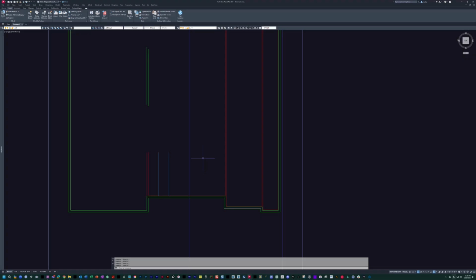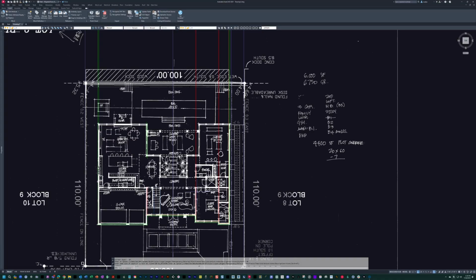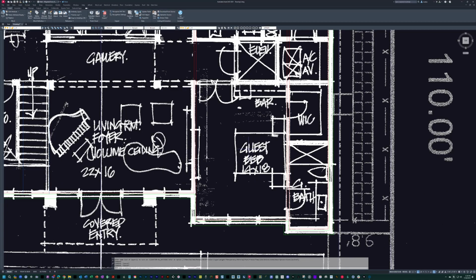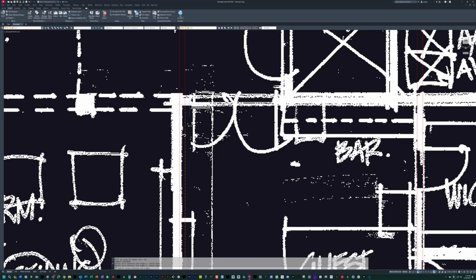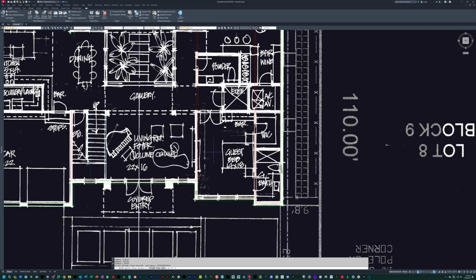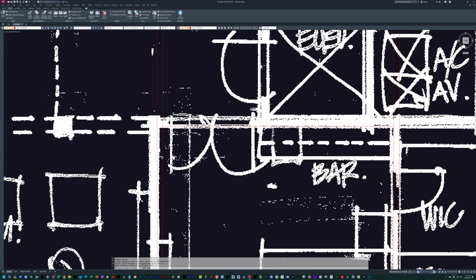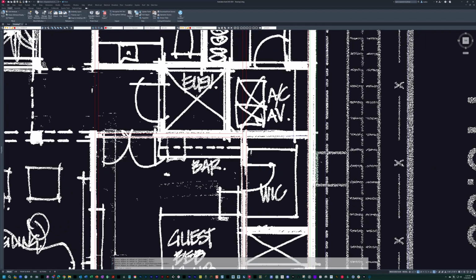Let's keep it moving. We're going to try and get all the spaces planned, and maybe we'll fill in one of them and talk through that a little bit. This is an 18-foot bedroom, but there's a bar, so I just want to verify if it's 18 to the bar or 8 or 20. 19, it's basically a 20 foot. So we're going to offset, we'll go W4 to 40. Again, W4 is just a custom Lisp I created, just as an FYI. If we want to see videos on that, we can do that.